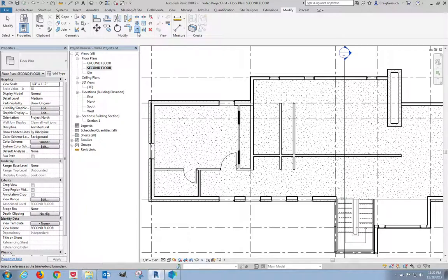All right. Now I'm going to use the icon one over, trim extend multiple elements. This works almost the same as the last command, except when I select the item that I want to extend to, I can extend multiple objects to that item in one shot. And it won't end this particular extend to that object until I left click on nothing. Now I come back down here and I'll click on this line because this is what I want to trim to. And I want to select both of these walls on the side that I want to keep them. Just like that.